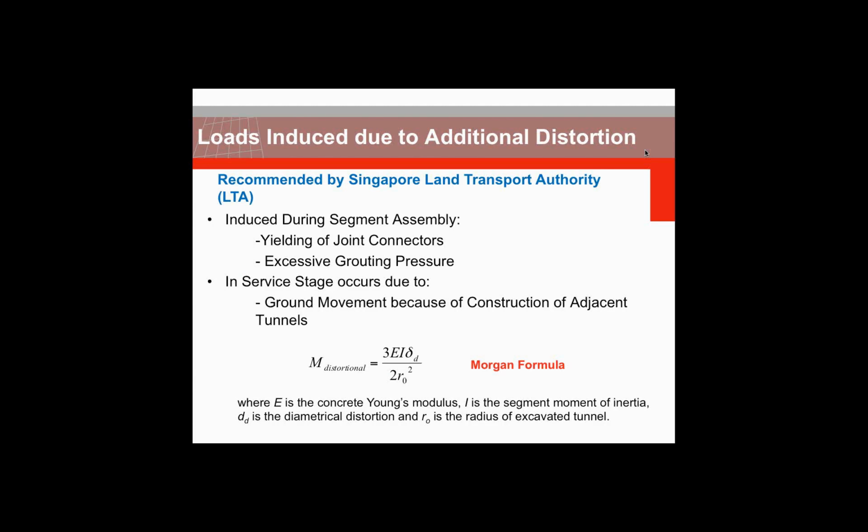Another load case that we consider is loads induced by additional distortion. This is a special load case recommended by some of the standards. One I mention here is the Singapore Land Transport Authority, or LTA. During assembly, some of these joint connectors may yield, or there might be excessive grouting pressure, or